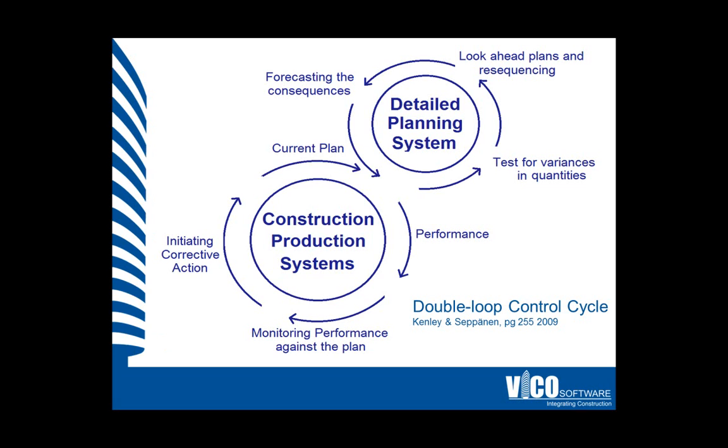A location-based model provides a lot of information in a plan that is not available in an activity-based model. This includes the flow of resources, the quantities by location, the production logic based on information gathered at the last planner stage, and the experience from one location, which is explicitly recognized and reflected in the following. The location-based planning model needs a compatible location-based control model in order to fully utilize and update its rich information base during the production phase.